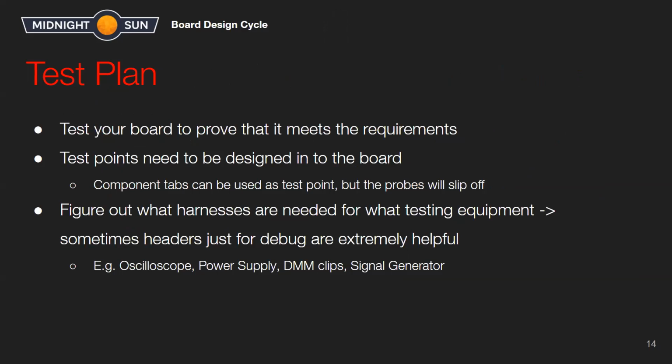Through that simulation, you'll figure out possibly some points that you might want to test in the future. You definitely want to test your inputs and outputs. Let's say there's one node of your circuit that has a derivative current. You just want to make sure it isn't heating up too much. That's what your test bed will remind you to do. It's always super important to make one, because then we have a record of what was tested on the board and what wasn't.